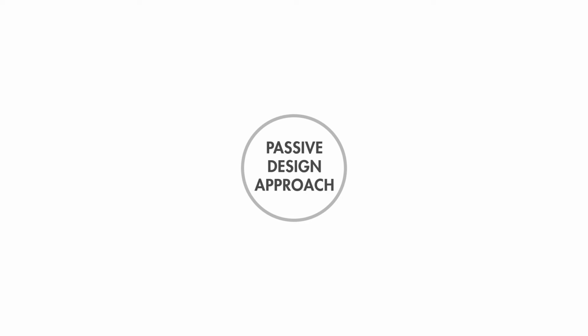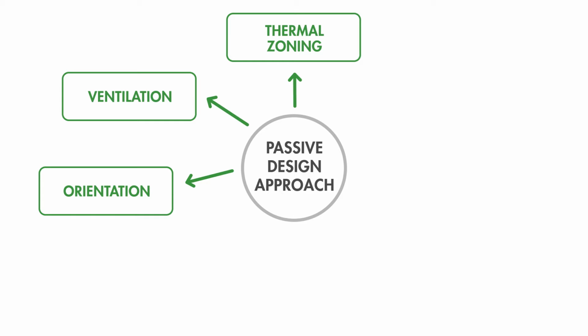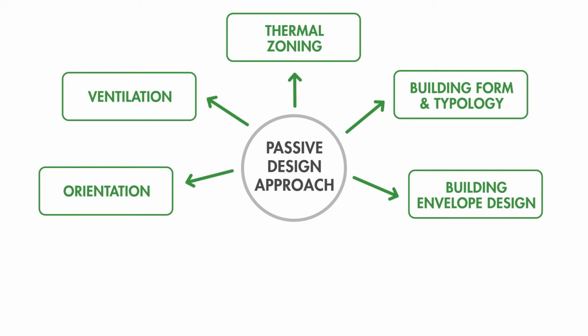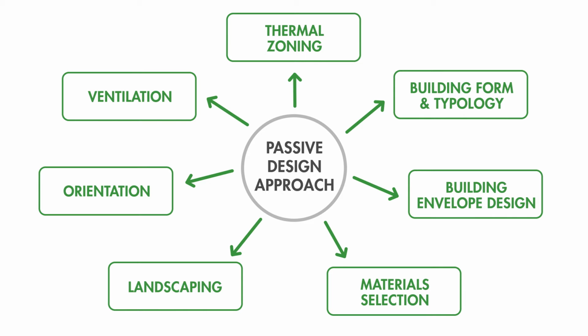The passive design approach consists of different climate-responsive strategies to avoid heat transfer through the building envelope: orientation, ventilation, thermal zoning, building form and typology, building envelope design, material selection, and landscaping.